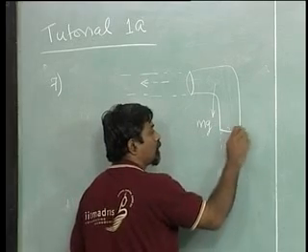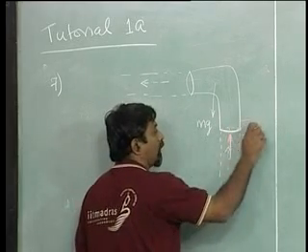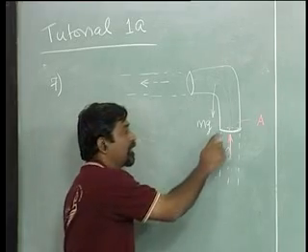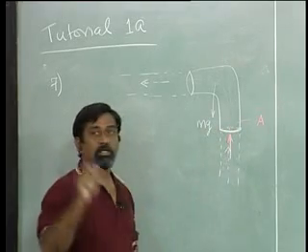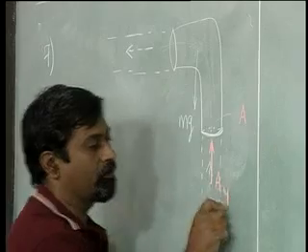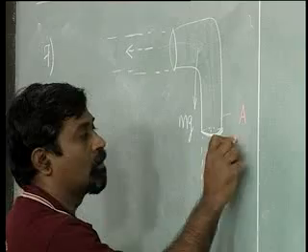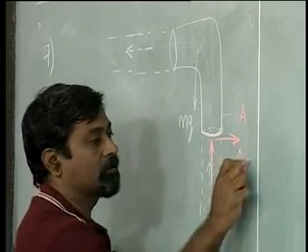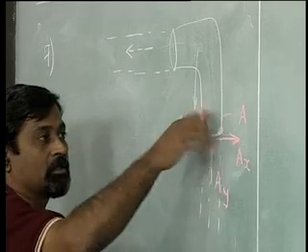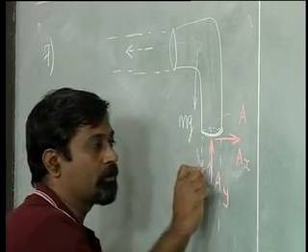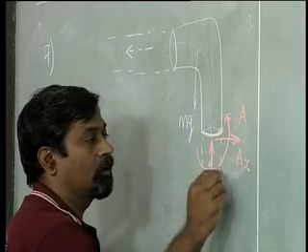Let us locate this point as let us say A. I am deliberately clubbing the entire surface into one single point. Okay. This is AY. There is also due to horizontal restraint, which is AX. Apart from that, it is not let to rotate because of this pipe, and therefore there will also be M at A.